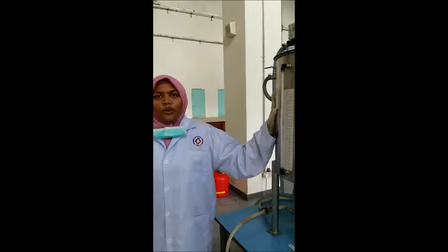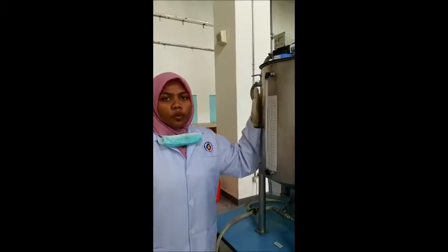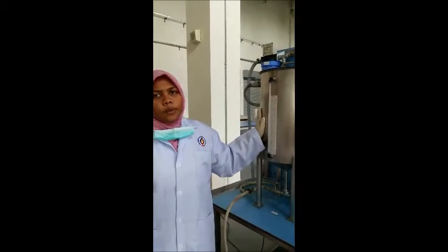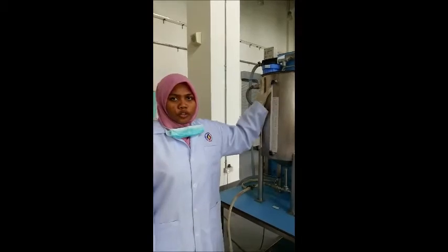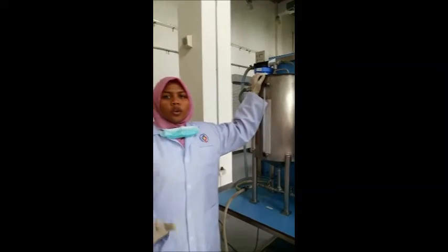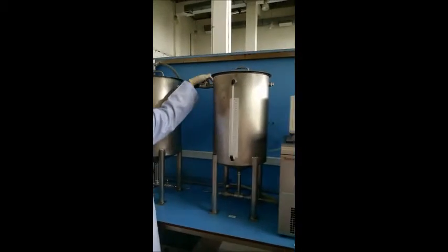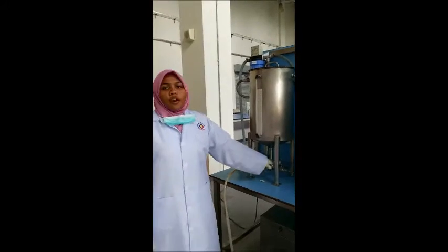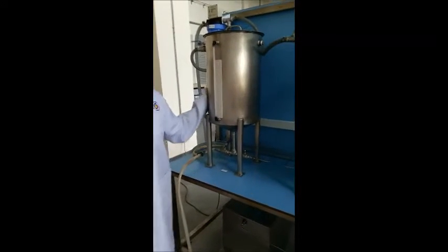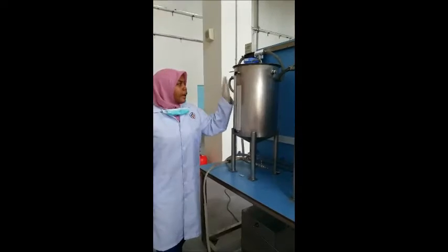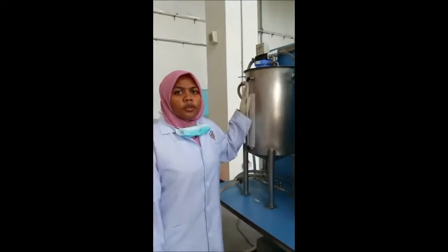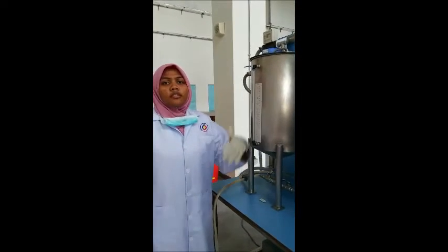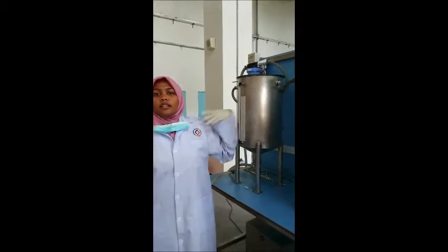By this process, only for flush, only tank 1 should be filled with water, because during the experiment, only tank 1 will be filled with chemical. So we flush only tank 1, and the water won't enter tank 2 unless the valve V12 is opened. Like I mentioned before, the valve is closed in order to ensure this tank is filled with water. As the tank is being filled, we will now open the valve V2 to allow the water to enter the system of the reactor at the other side.